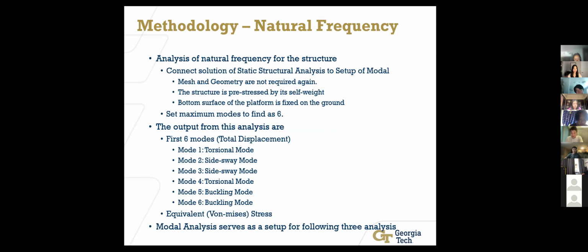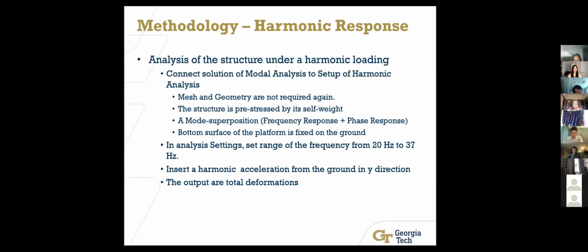Then we set the maximum modes to find to 6, and the output from this analysis is 6 modes shown here, and extra equivalent stress. And the modal analysis serves as a setup for the following 3 analyses, because the response spectrum and the harmonic response are just a superposition of these natural frequency modes.